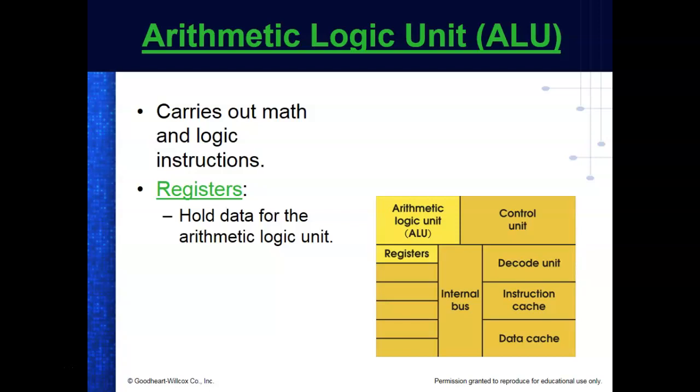Then we have what we call registers inside the microprocessor, and the guy that wrote this book does an awful job on registers. He calls everything registers. Technically, the only place registers are is inside the microprocessor. So a register holds the data while it's being processed. If I was going to add two numbers together, normally we'd load one into one register and load another into the other register. We'd add them together in the ALU, and then we'd put the result somewhere.